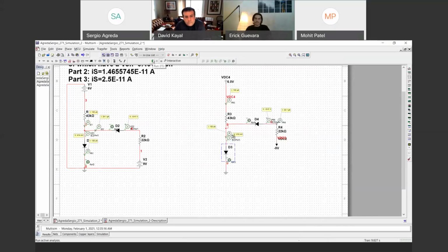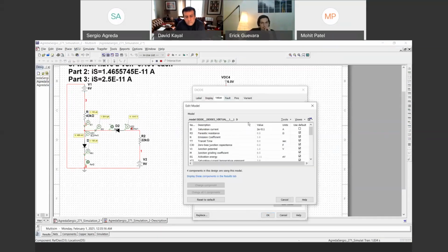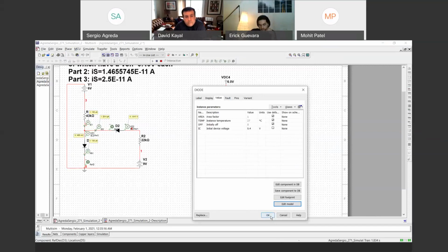Stop the simulation, run again. This is getting closer. Same current that we expected and calculated. Same with the voltage across this diode that's off. It's still close, but let's see how far we have to increase it. Let's just go with 2.5 already, because that's what will help our diode behave like we calculated it to, or at least to an extent similar to what we expected.